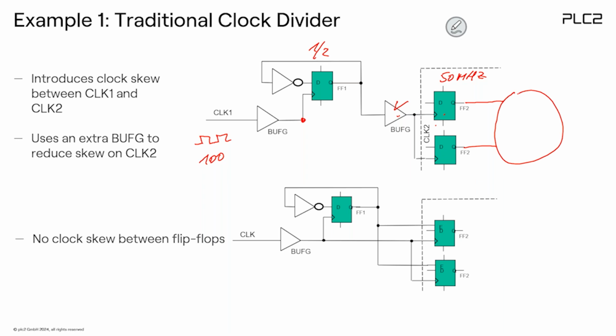But if you later on would like to do something like this, to use again my master clock, the first clock, to register data, this will fail again, because the relationship, the phase between here and here, is actually not known. You have a delay here, you have a clock to output here, and you have a delay here, so it's not known. So this is not correct.